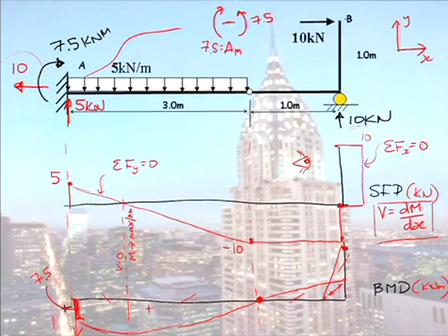So, what's the moment here? If I cut the beam here with 10 here, what's the bending moment down here equal to? 10 times 1? So the moment here is 10, and going round a corner, it has the same value. What I'm saying is when I cut a horizontal beam, you're quite happy that that moment equals that moment. When I cut round a corner, the moment on the horizontal leg equals the moment on the vertical leg. So they're also equal. So that 10 must equal that 10. We've got 7.5 here. All we're left to calculate now is that maximum moment there.